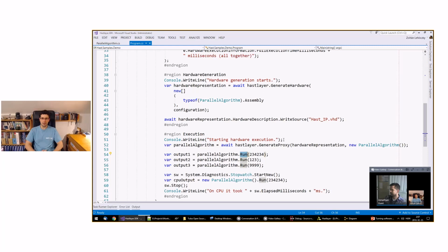Yeah, that's also a good question. First of all, it's intermediate language to VHDL. So any compiled .NET application can be processed here, as long as the intermediate language code won't be too alien, but usually the different compilers still produce pretty similar results with the same code structure. What you ask about, if I understood correctly, is also a bit of a high-level synthesis use case. That's what I mentioned, that you can do that, but we don't support it specifically.